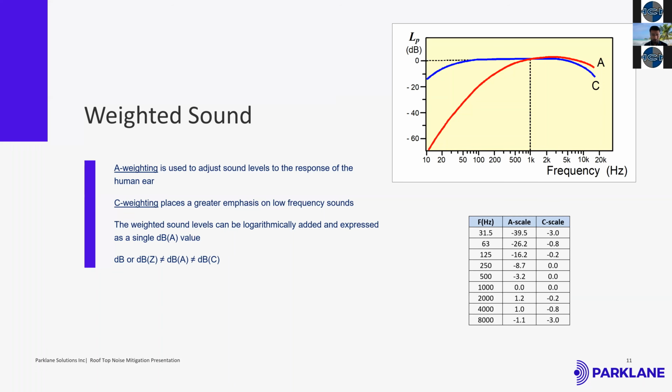The curve in red, called the A-weighted scale, is a very fair representation of what a human ear can actually perceive. In the lower frequencies, you don't really hear a lot of the high-amplitude sound, and that's just the property of how your ear works.